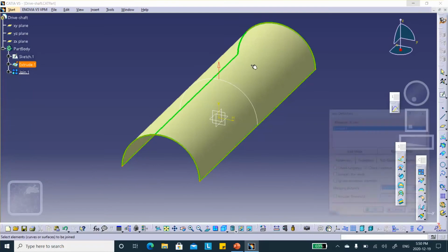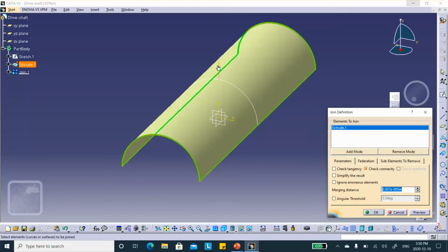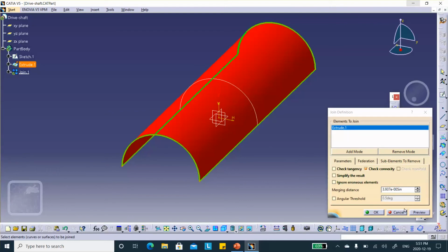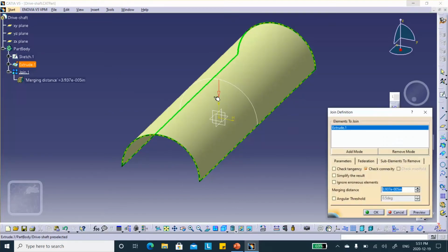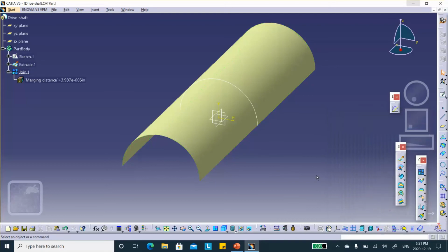If you double click on it, notice that it gives you that arrow. That means that the shell elements that you use to cover this surface, their normal is opposite to this, and I don't like that. I want it to go in the other direction, and that'll do it. So if you double click on it now, you see that it's pointing down. Okay, this has nothing to do, by the way, with the direction of draping and things like that.